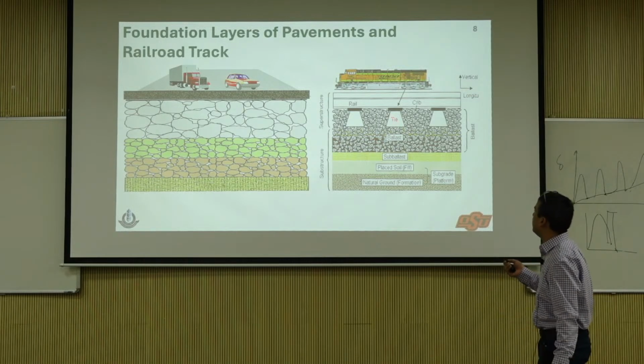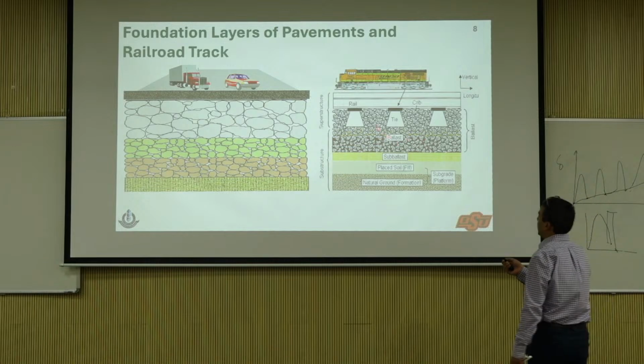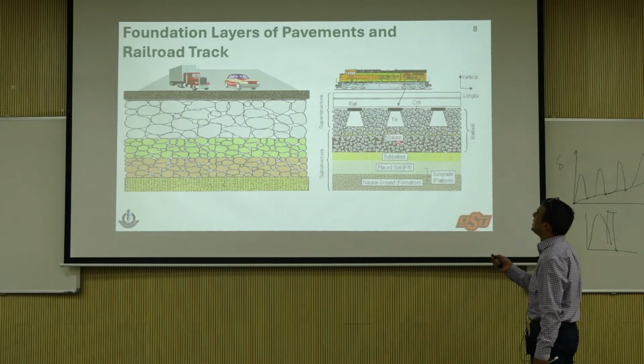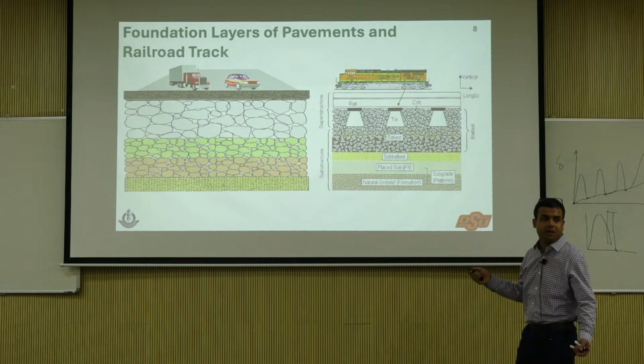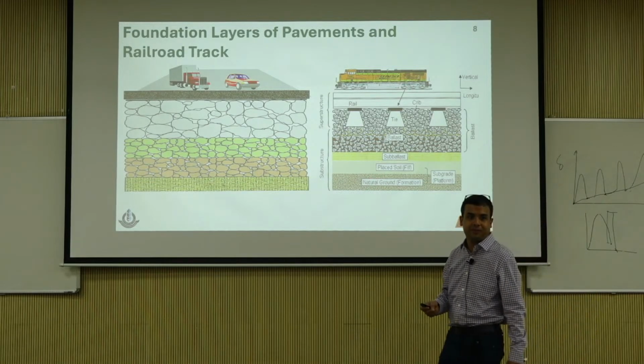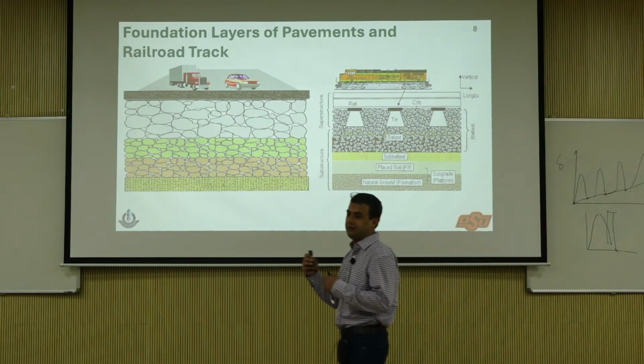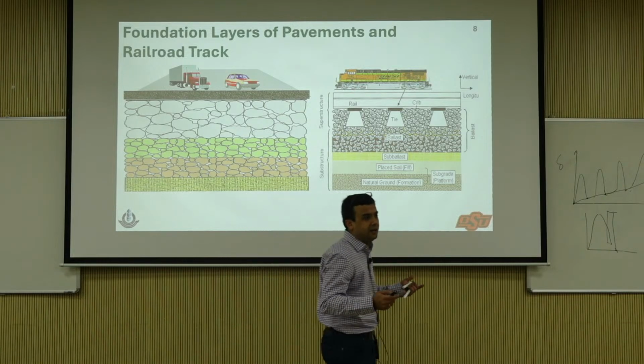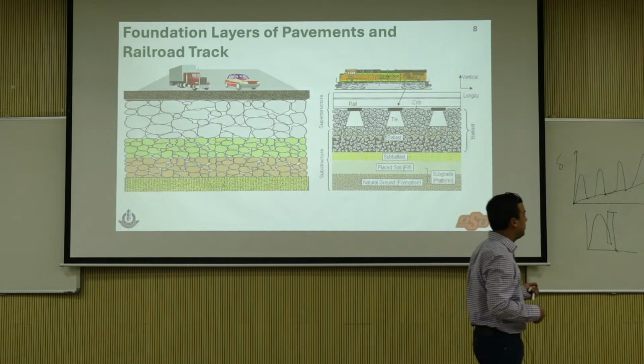In North America, you call it cross ties. Then you have what is known as railroad ballast, which is the coarse grain. So basically below this, folks, you can think of this as base, subbase, compacted subgrade, natural subgrade kind of stuff. Similar stuff. Gradations are different, material is different, load levels are different, thicknesses are different, but the mechanics is exactly the same. There's no difference.